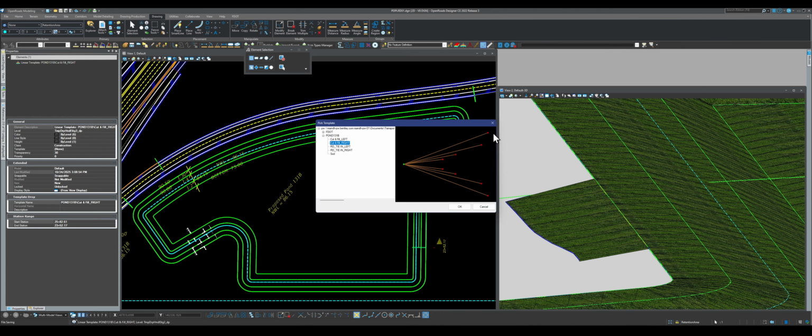As you see, all these, like the bunch of conditions, we tell it to go from this point, which is from here, and then start hitting the surface. And you usually start with the lowest one. It will try the 50%, that 1 to 3, 1 to 4, 1 to 5, 1 to 6, basically. Either cut and fill. If it is low on the ground, it will use these first. If it's up the ground, it will try to use this. And it tries to solve the equation. That's it, and mimic to the ground.